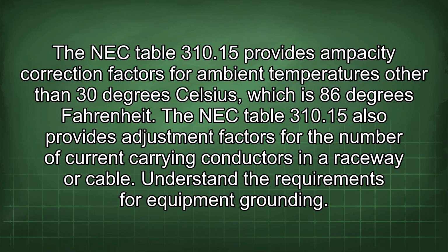The NEC Table 310.15 provides ampacity correction factors for ambient temperatures other than 30 degrees Celsius, which is 86 degrees Fahrenheit. The NEC Table 310.15 also provides adjustment factors for the number of current-carrying conductors in a raceway or a cable. Understand the requirements for equipment grounding.